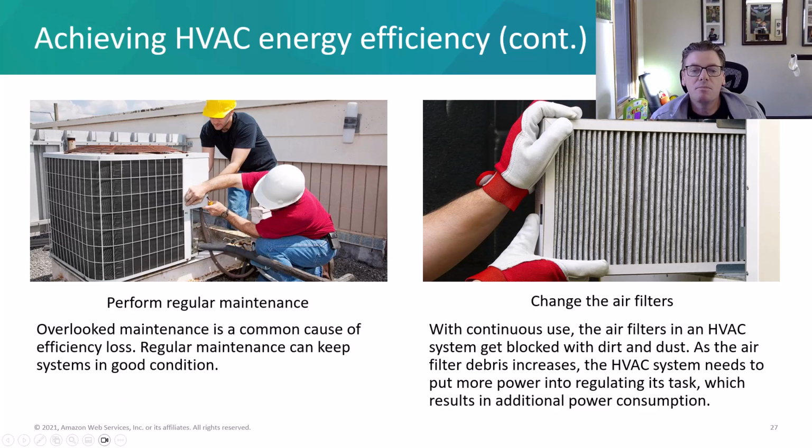All right, performing regular maintenance. Again, this is something we want to keep the system in good condition. We want to change the air filters regularly as they start to fill with debris. It takes more power to pull the air through that air filter.